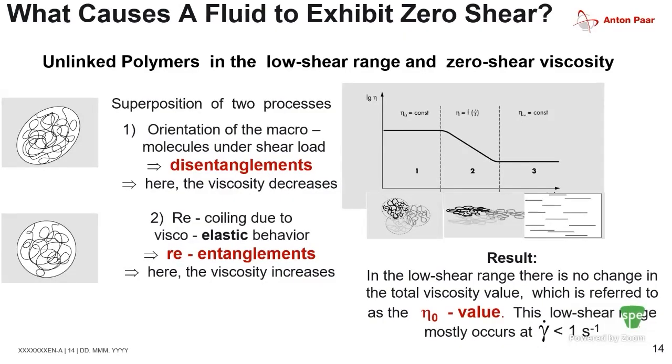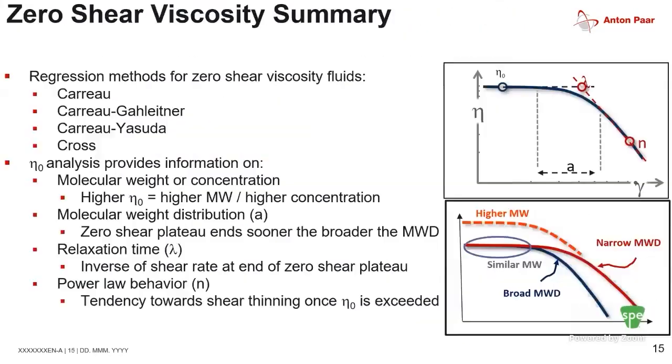And so from this, we can get some information from modeling as to what the zero shear viscosity is. In the case of this, the zero shear viscosity is important because from that, we can garner that information out from various models: the Carreau model, the Carreau-Yasuda, the Cross model.